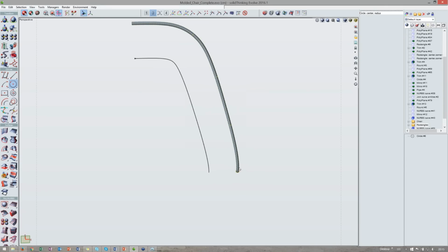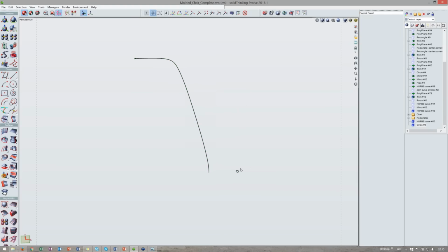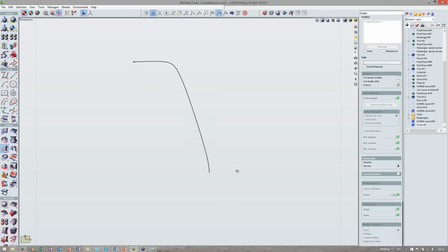So we decided to give this sweep tool a nice twist. If you look closely, you can activate another functionality of the sweep tool pressing Control. So Control on the sweep tool, and in this case it invokes an auto alignment functionality for the sweep. What does this mean?